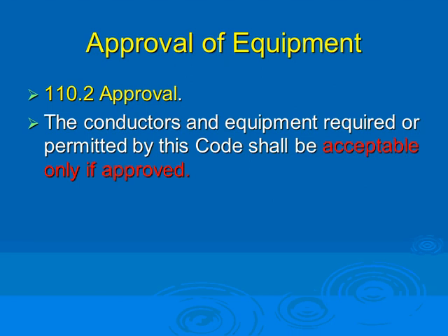I mean, if UL says this switchgear can handle 85,000 amps, and I'm willing to put my name on it as an engineer, can you say no? As a registered engineer, I don't feel comfortable saying no. I don't have the equipment to test them. So the authority having jurisdiction, typically, if you have third-party verification, will accept it. Otherwise, you have to go to a list of engineers to get you the approval.